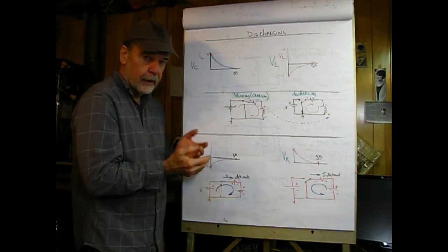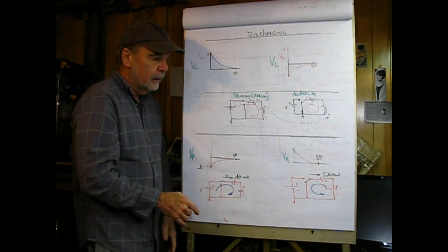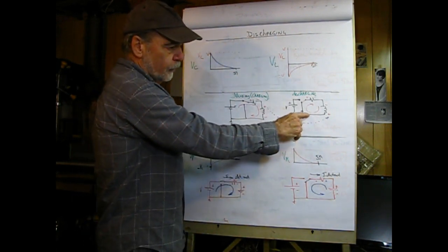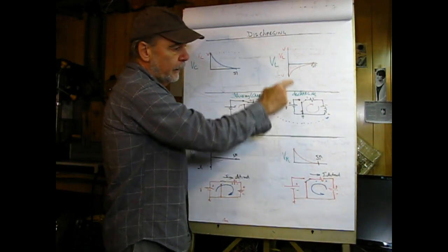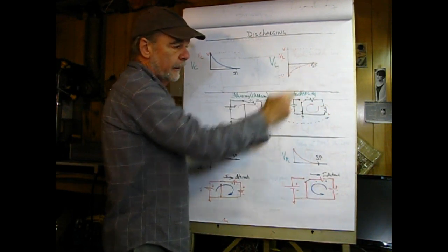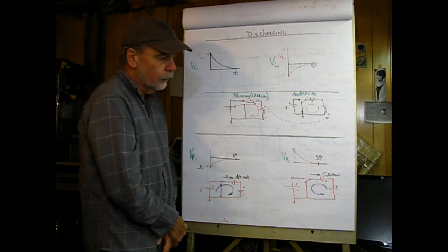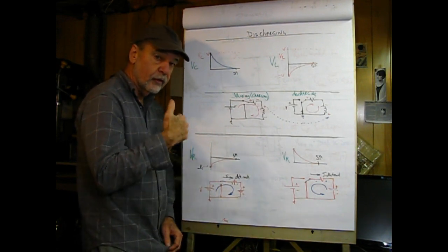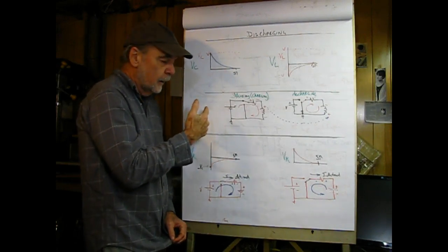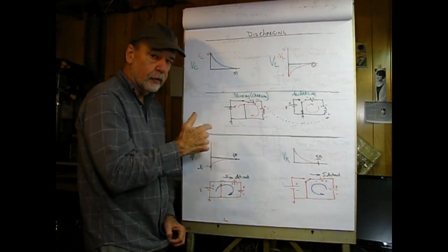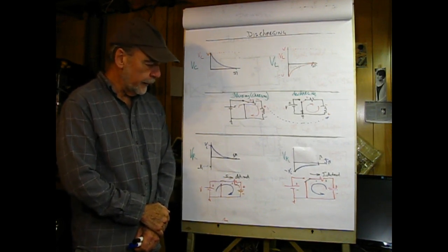So the core of this is that inductors want current to remain the same and capacitors want voltage to remain the same. Now when we charge this here, what we see now is, relative to ground, the top of the inductor is now negative, hence down, and then it exponentially decays. So that switching of polarities is why the current flow in a discharging cycle is in the same direction as the charging flow, where in a capacitor, if you remember, the discharging current flow was in the opposite direction to the charging flow.